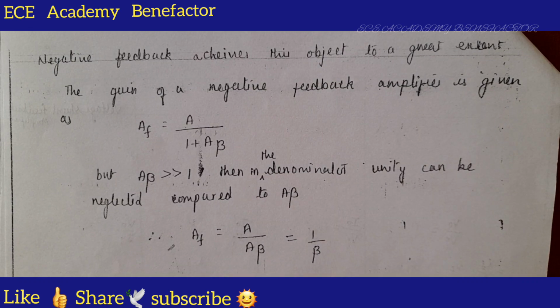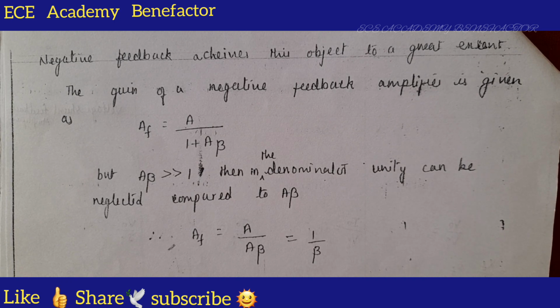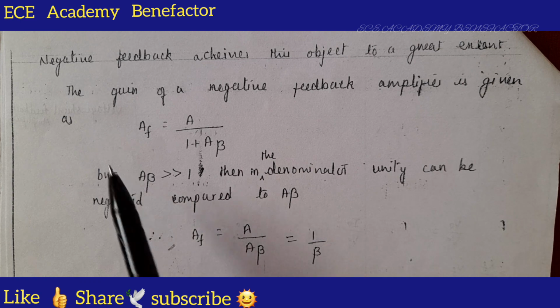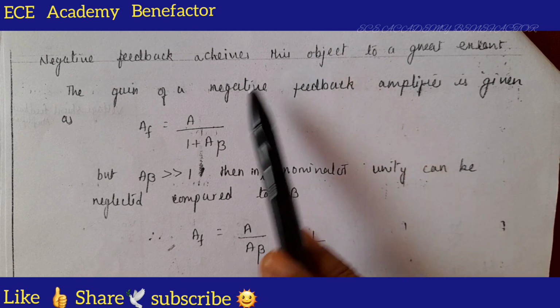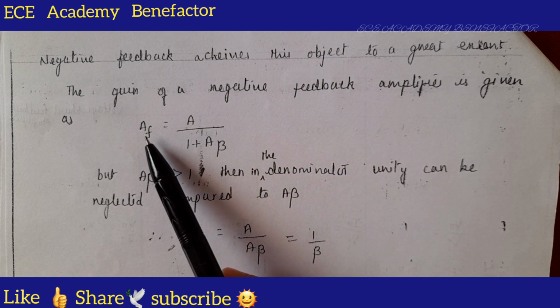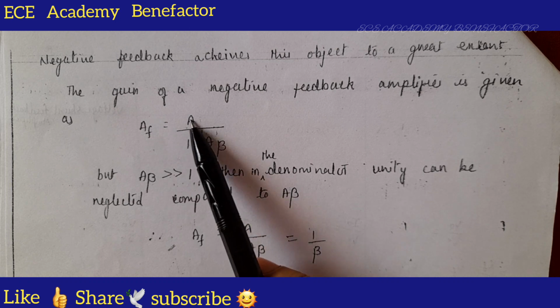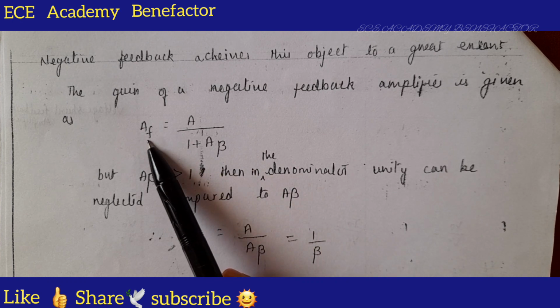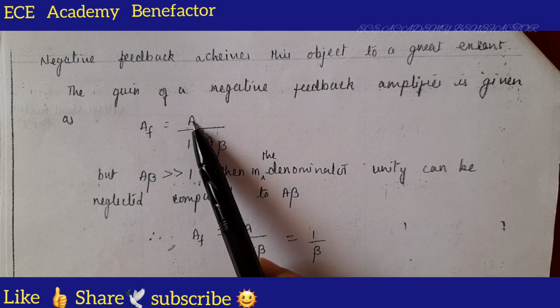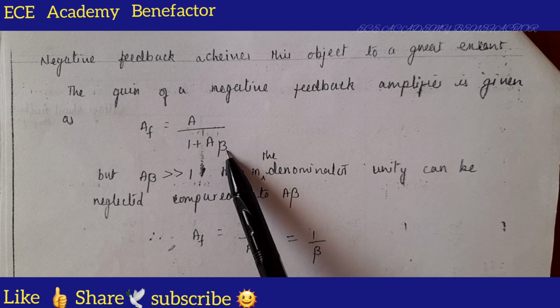Negative feedback achieves this objective to a great extent. What is the objective? The gain of the amplifier is to be stabilized. How can we stabilize the gain? By implementing negative feedback to an amplifier. That's written here. The negative feedback achieves this objective, that is, the stability of gain. So what's the gain of negative feedback? The gain is given by AF is equal to A by 1 plus A beta. This is the gain of negative feedback, where AF represents the gain with feedback, A is the gain without feedback and beta is the feedback ratio.